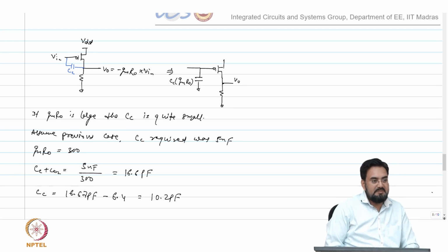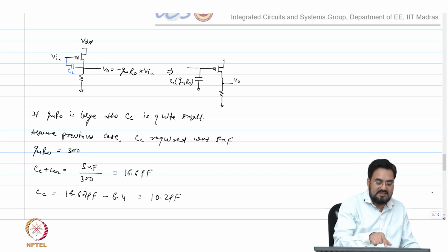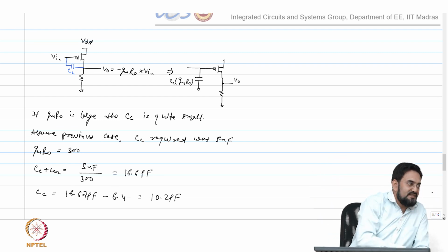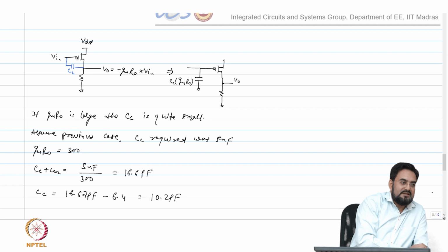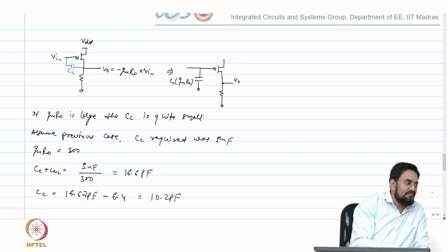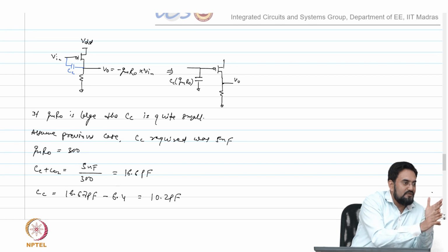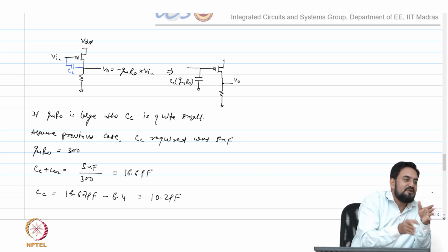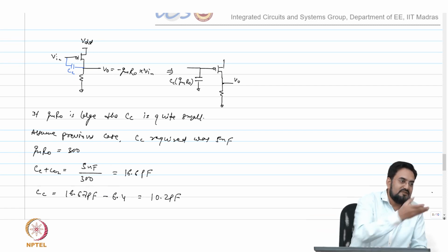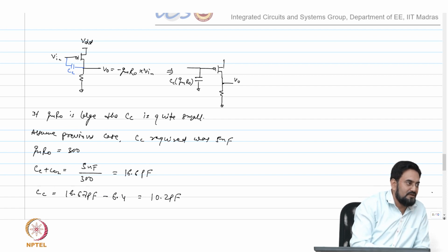So one thing you need to remember, now this capacitor is a function of your gain, and the output stage gain is changing with the load current. Okay, so you have to make sure that at the maximum load current, this capacitor will get smaller, which means your omega P2 will move to a higher frequency, but at the same time your output pole is also moving to a higher frequency. So if both are tracking well, then your phase margin will not degrade, but your bandwidth will be increasing actually. So that will not hurt, it will further improve your transient response and all those.